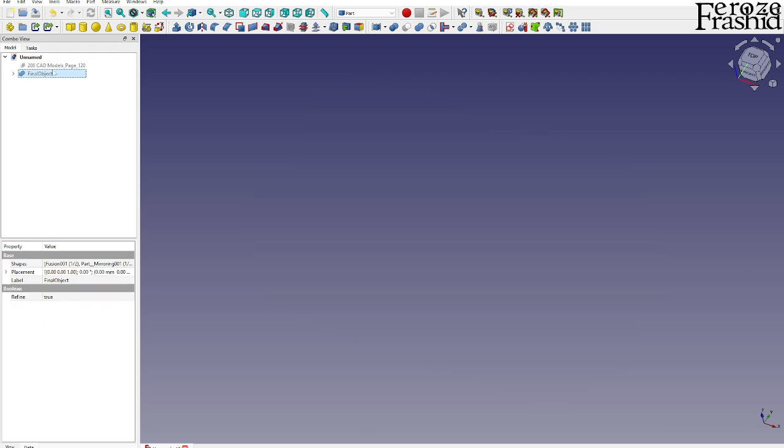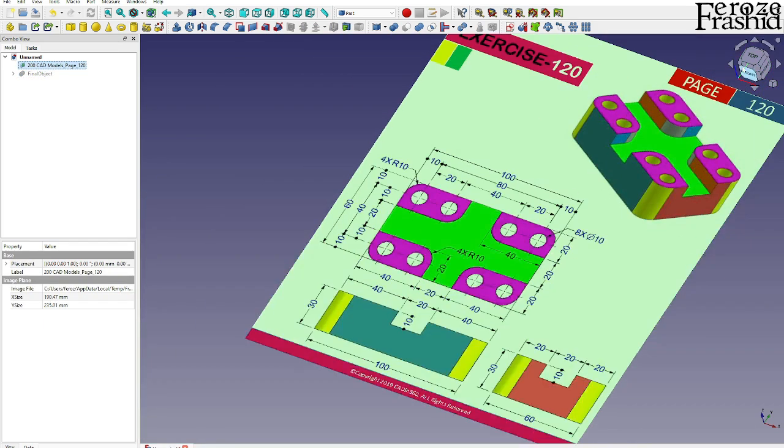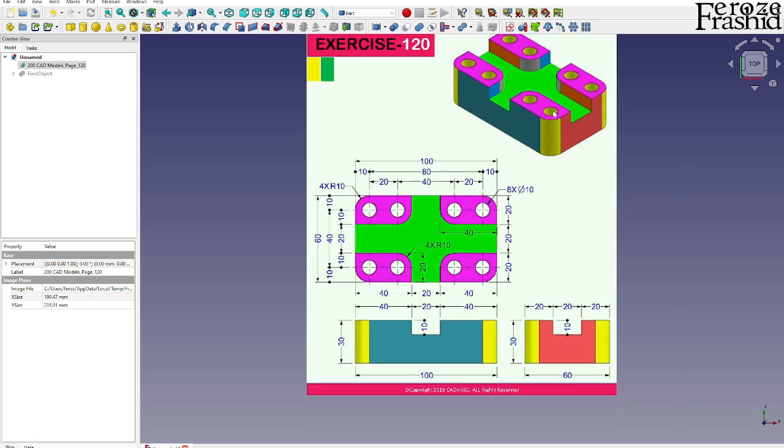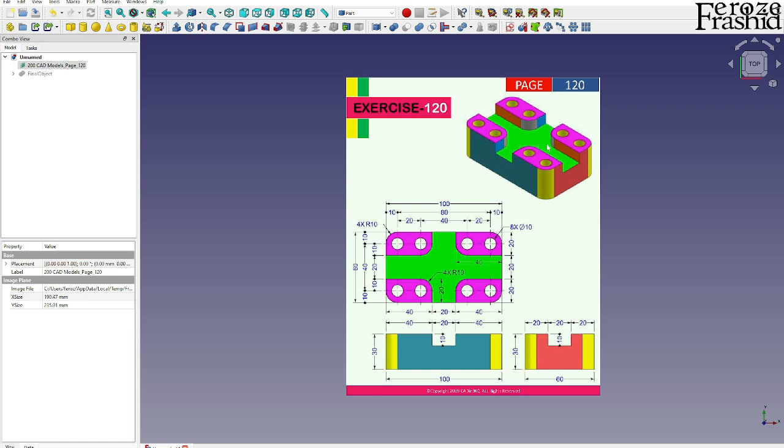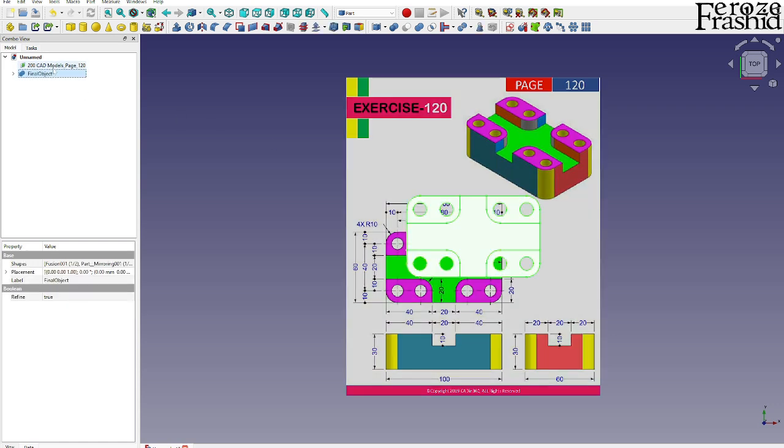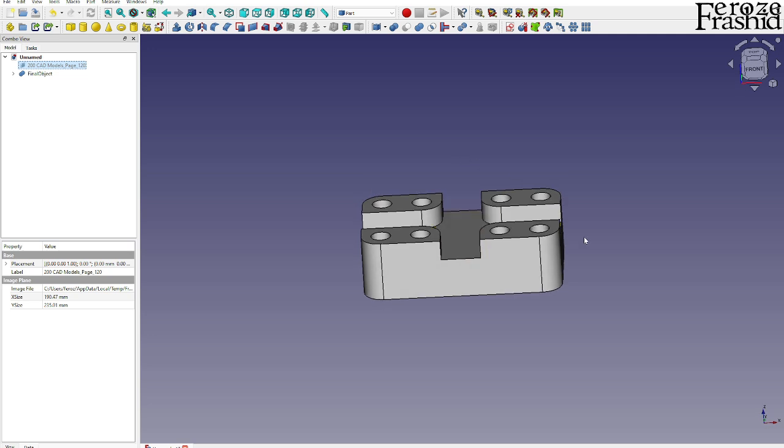One thing I would like to note though, is that this technical drawing is not sufficient. These holes, it appears they are through holes, so that's what we built here, through holes, but it could end at any point at this height, and to do that we need a cross section that goes through these holes, or at least some dotted line, hidden visible lines in here. So that's why the cross section, or hidden lines, dashed lines, are important in technical drawing. So I will put the technical drawing in here so you can download it and see what I'm talking about.